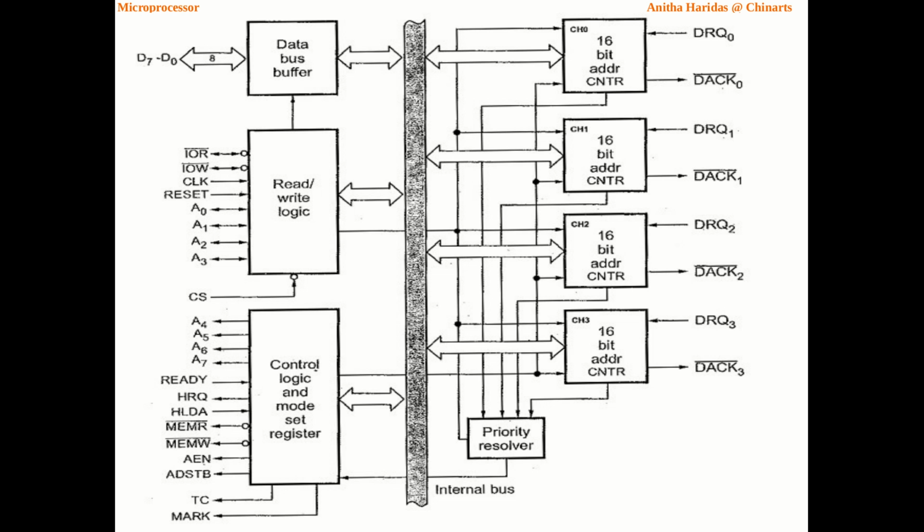So when the register is selected by the CPU, the first 8 bits will be written from the D0 to D7 lines, then the second 8 bits will be written to the most significant byte using the second clock pulse. Now the address register is filled by the CPU.